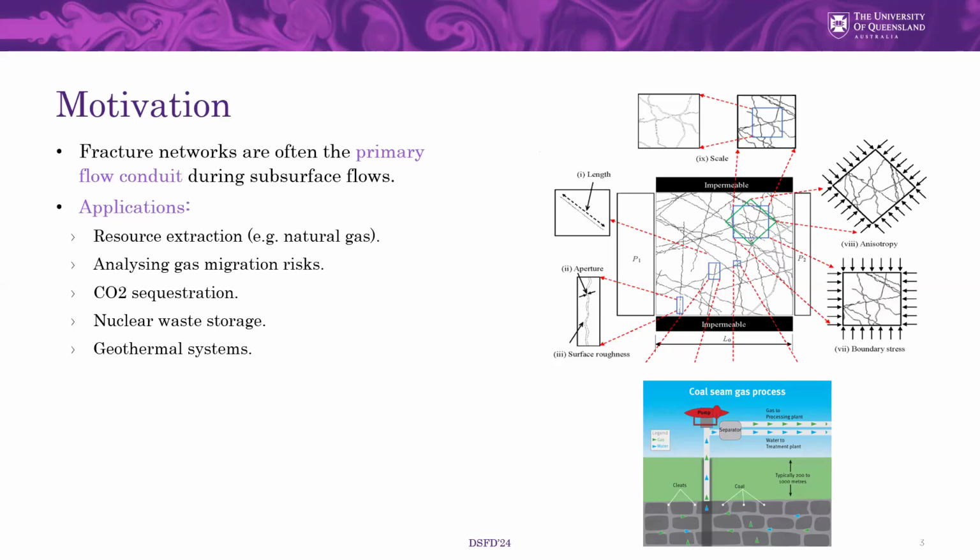So this is going to the end of the life of the wells, where you can have fractures in the cement around the well field that can allow gas to migrate to other areas that you don't want it to actually be present, particularly because a lot of the work that we do is in agricultural regions as well. So they drill lots of water wells and they don't have the type of technology they need to deal with gas kicks if they hit a particularly gassy pocket.